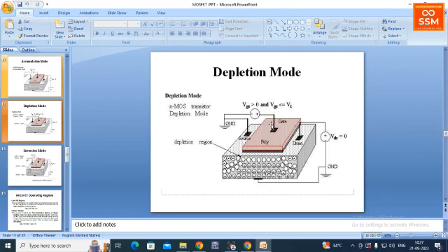So what happens inside, if gate source voltage is given across this gate terminal, but it is very low, here it is less than VT, so we are going to provide a gate source voltage which is less than VT, since it is a positive voltage. This positive pulse which is nearer to this region, I am showing with the cursor, just listen. So here the holes which are deposited here are going to be repelled by this positive gate source voltage, and pushed down.